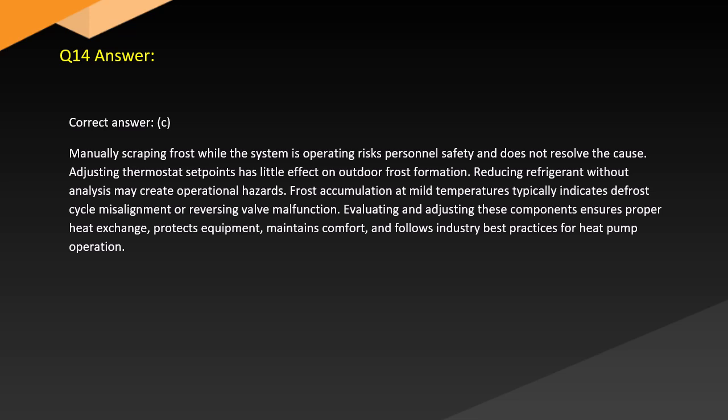Answer. Correct answer. C. Manually scraping frost while the system is operating risks personnel safety and does not resolve the cause. Adjusting thermostat set points has little effect on outdoor frost formation. Reducing refrigerant without analysis may create operational hazards. Frost accumulation at mild temperatures typically indicates defrost cycle misalignment or reversing valve malfunction. Evaluating and adjusting these components in proper heat exchange protects equipment, maintains comfort, and follows industry best practices for heat pump operation.